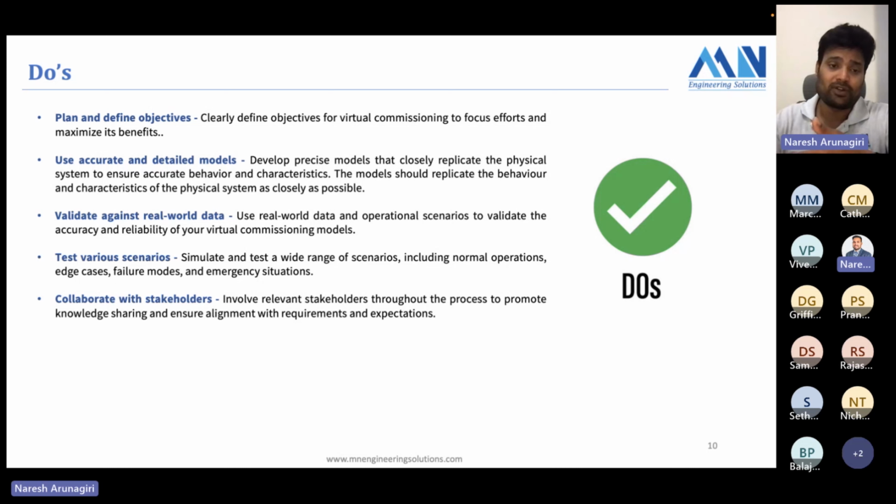When you have the environment around you, as I said, we took out all the fail-safe controls, all the fail-safe PLC interface blocks. We got rid of all the guarding and stuff because we know it is not required at this point of time. We actually checked a full cycle machine later on with all the guards and stuff. But here you've got to see what is actually required and what details you are trying to simulate as real as possible, as the real world data. So make sure you're cleaning up all your boundary conditions and defining your data sets based on it.